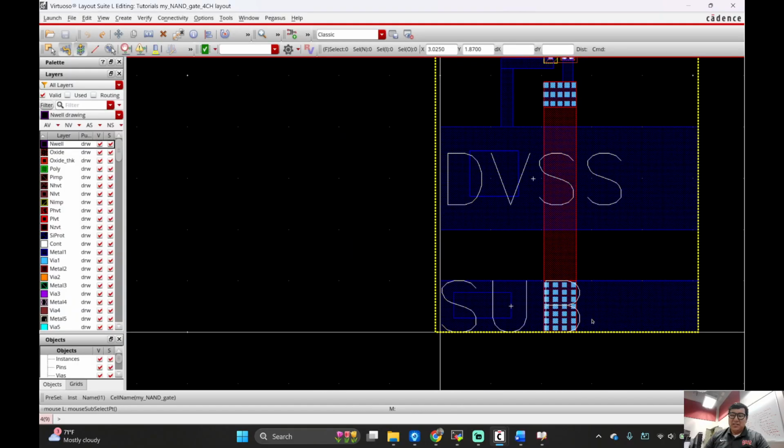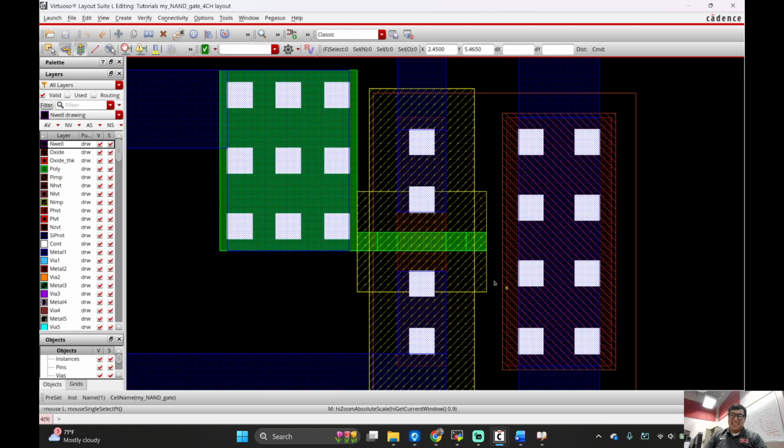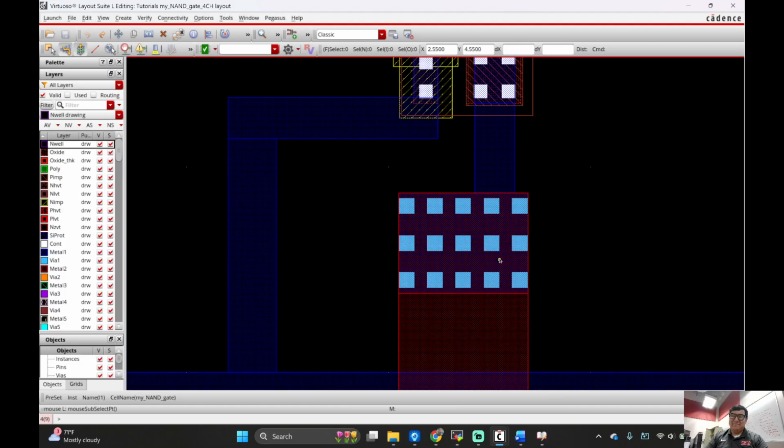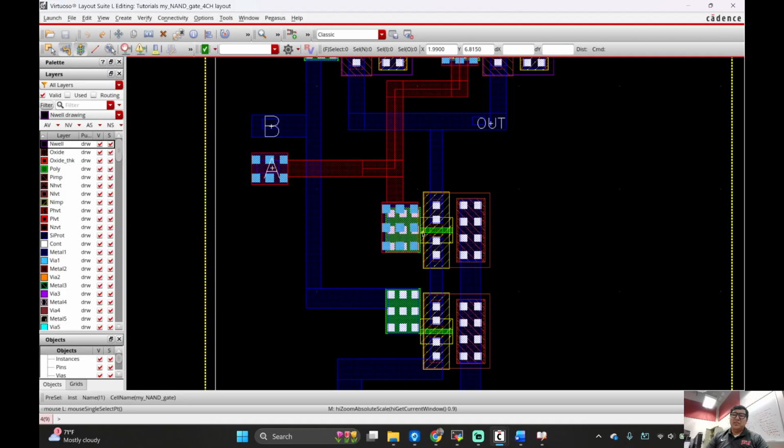It's pretty chill. This is my sub, and then oh yeah, I rotated my transistors. So you know how I had them all like flipped one way, but I flipped them the other because then I can do this cool waterfall trick. Like, oh, I can just pull it from here and boom, waterfall like that. And you see these bodies? I could just connect it like this. Cool. And then look at this waterfall from here to here. But if you wanted to investigate this, be my very guest, you can use 2-finger device to let you see how you can connect this and this all together into one. You can make this really, really tiny if you wanted to, but for demonstration purposes, this is what I did, okay? And then here's the gate.